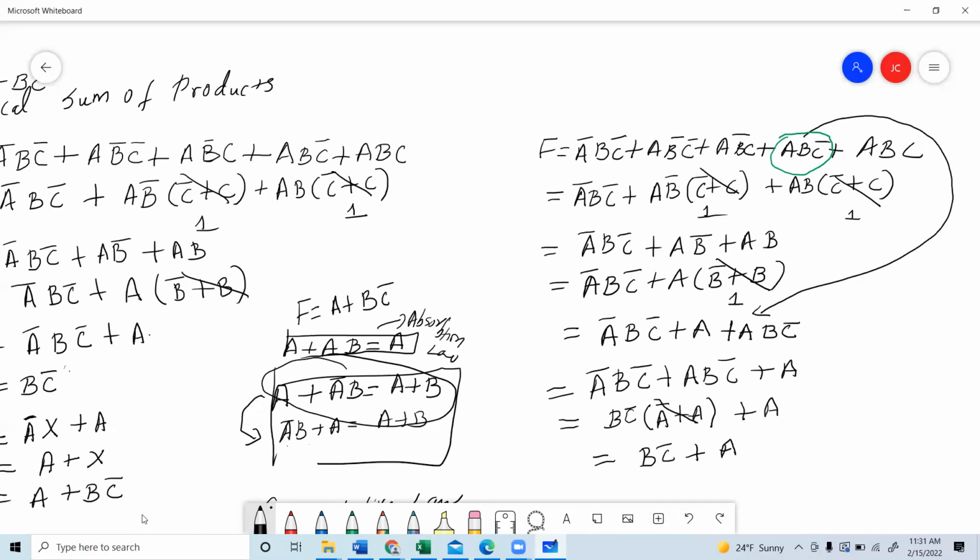Now, in the sum of product form, for which output is 1, that's very important. These are the min terms for which output is 1, right? So we can use any of the min terms again, reuse it and solve it. These are called min terms. Each row in the truth table is called a min term.